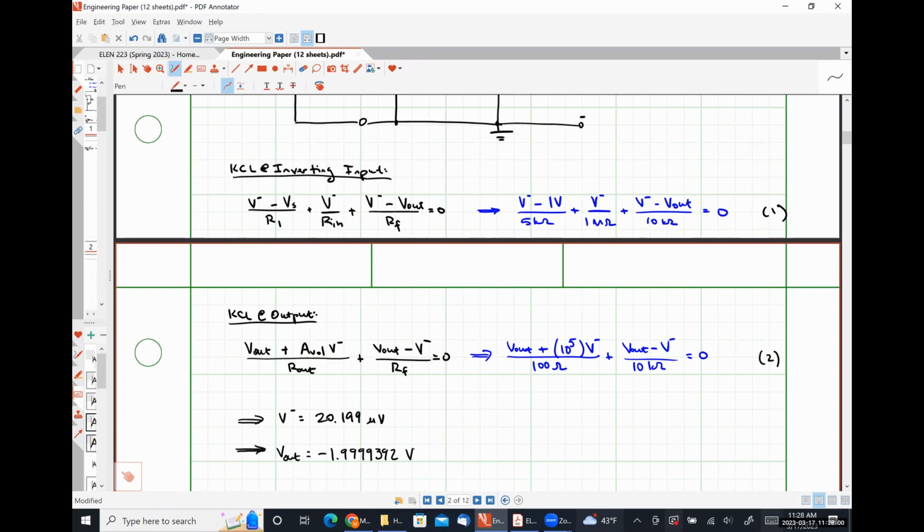You might call it 0 or something close to that, right? What do we know from Circuits 1 about the potential difference between the input terminals on an ideal op-amp? It's 0. So in a practical op-amp, it's not 0, but it's real close, right? That's because this input resistance is so large and this voltage gain is so high.